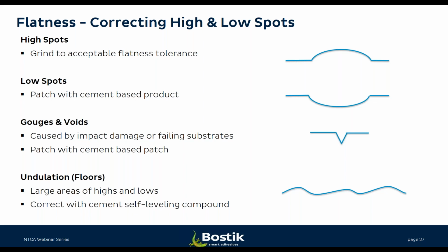Okay, so the low spots and gouges and voids could be, in some cases, a result of failing substrates or impact damage. Those areas can be filled with a patch as well. And then the large undulation that exists in floors can be covered with self-leveling underlayments.